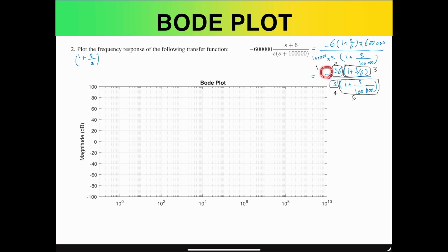So in terms of the magnitude, we won't consider this in general. However, it'll show up itself in the phase, which we'll discuss in the next slide. So in terms of the magnitude, we'll start with this 36. And we already know that for this, to consider part 2, I will just write 2. We need to consider what would be the 20 log of 36. And if you simplify that, you would get to a value of 31.